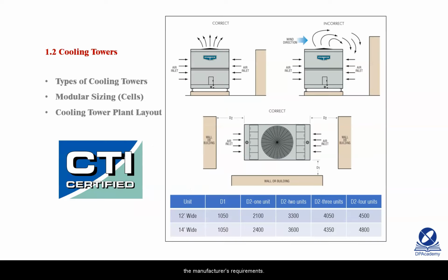Typically, all cooling towers will come with a CTI certification. This is a performance certification, and the manufacturer will ensure that the cooling tower performs to the requirements that it's specified, but on condition that the cooling tower is installed to the manufacturer's requirements. If not, the manufacturer will not honour the CTI certification and will not take responsibility for the performance of the cooling tower.